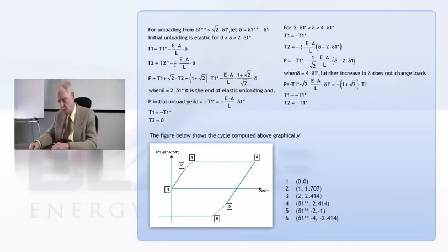And nevertheless, it's higher than you would get if you just say, I yield the same when I come back. So it usually turns out when people have tried to make some sense of Bauschinger's effect that you get something between no work hardening and Massing's hypothesis.